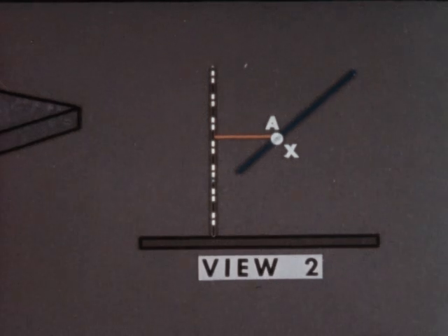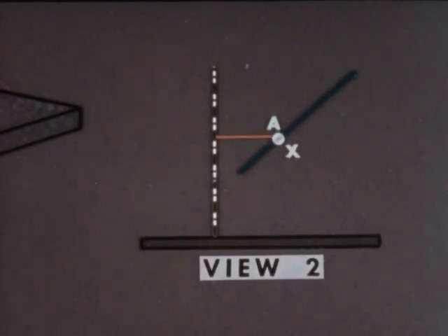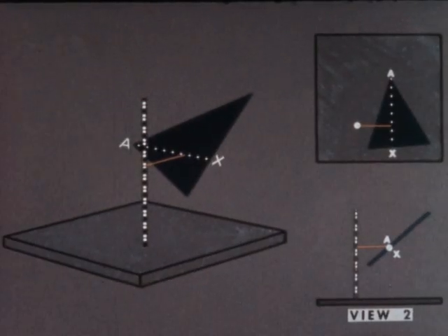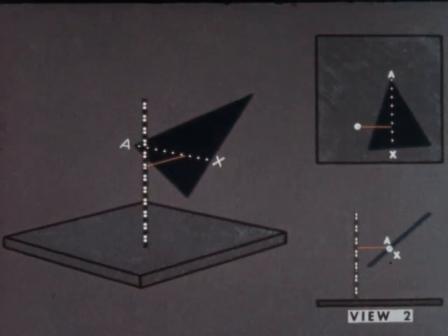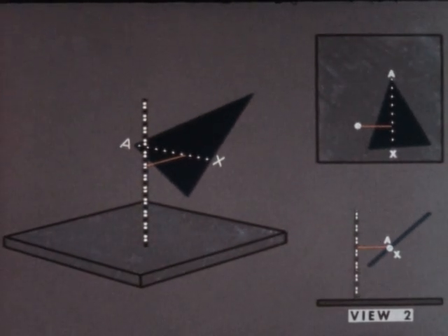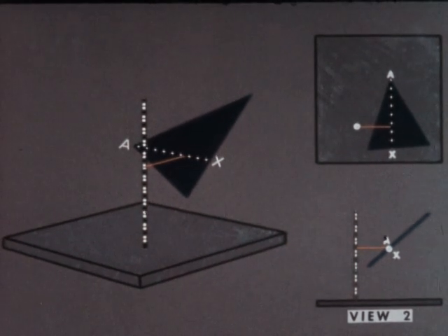You will note in this example that the axis is vertical and the line on the triangle is horizontal. If desired to see the triangle as an edge in the top view, use a horizontal axis and a frontal line on the plane.